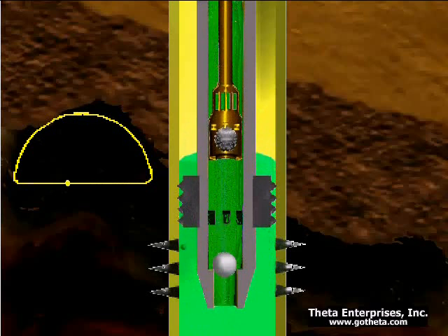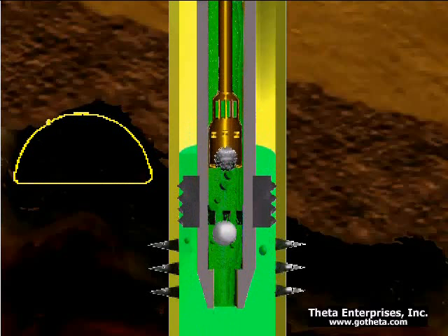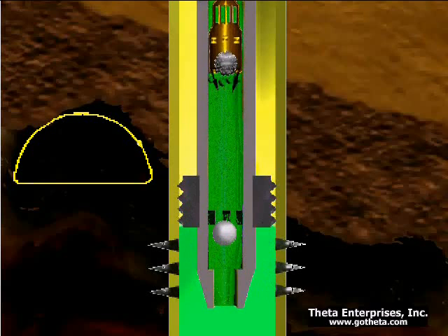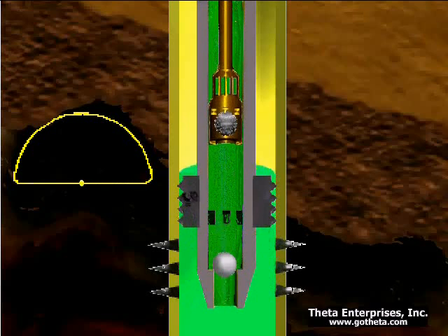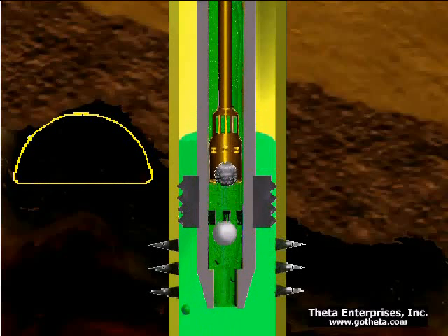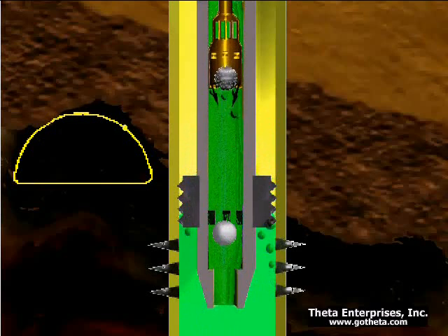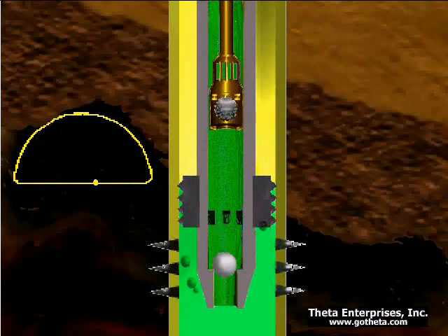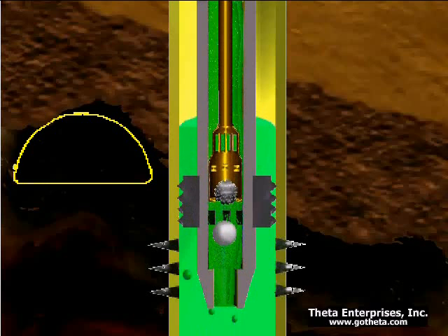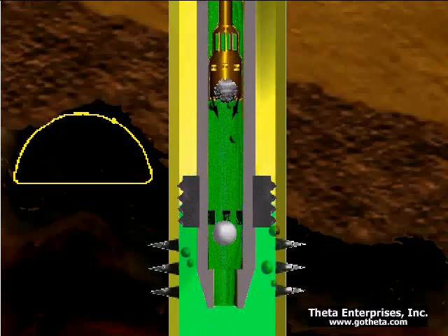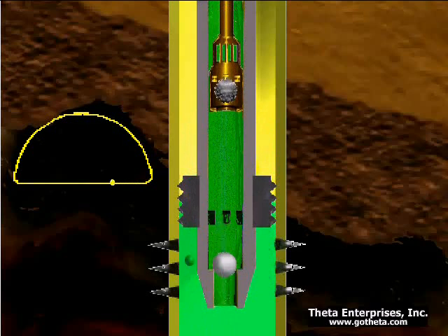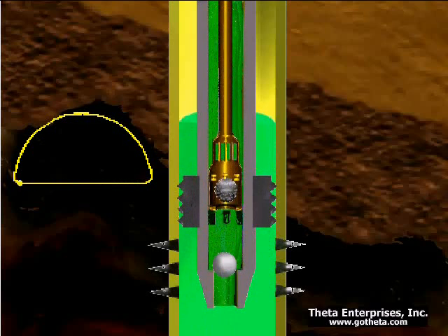Since the pressure difference across the plunger is what determines the load on the plunger, when that leakage occurs, the load is not going to be as high as with a full pump, and it's not going to build up as fast. It'll pick up more load as the plunger speeds up, and when it reaches the middle of the upstroke, you have the highest speed, and that's where you're going to have the biggest pressure difference.